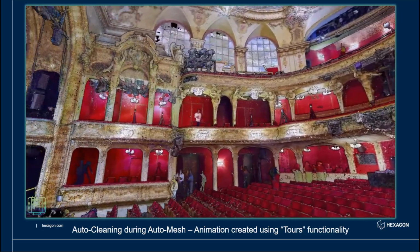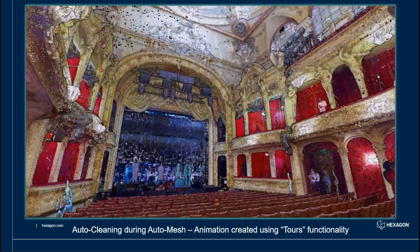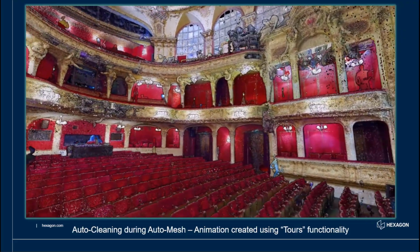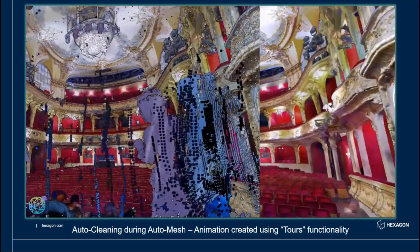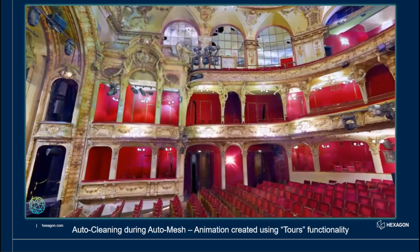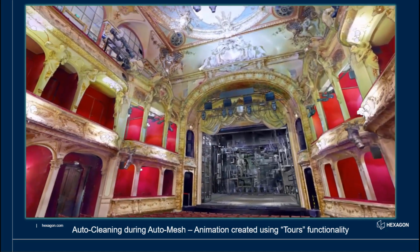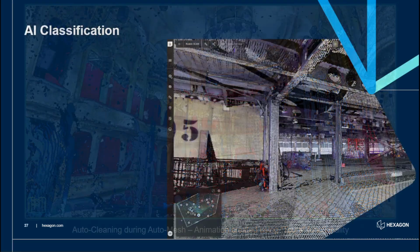So here's a point cloud. The animation was generated using our Tours functionality within HxDR Reality Cloud Studio. And in a second, you'll see this revert to the mesh. And it really is just to clarify that the mesh has been created fully automatically. So you just go in and say, create mesh, choose the sensor, in this case RTC 360, and then it's generated everything that you can see there fully automatically within the platform. So that is your auto mesh and your auto mesh cleaning as part of the platform.